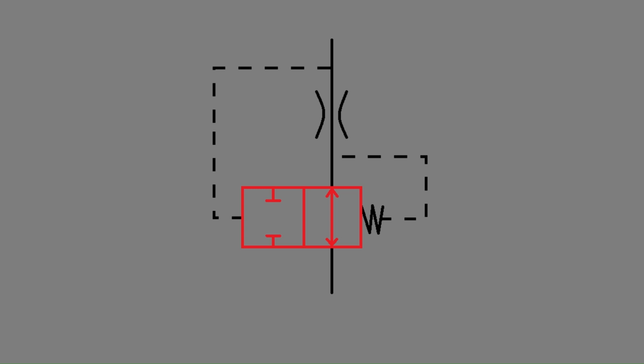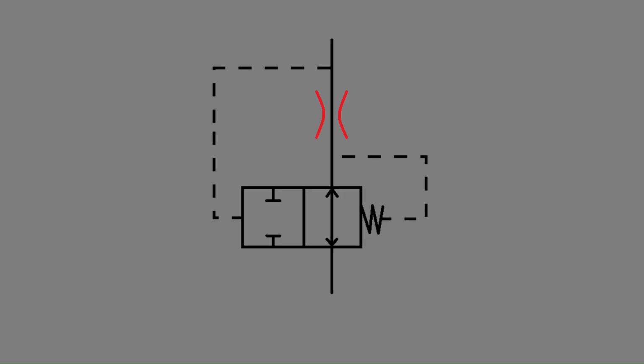At first glance, it may seem that the spring is setting the flow rate. A lot of other hydraulic devices behave the same way, where the spring is setting whatever we are controlling. However, the spring is setting the pressure drop, not the flow rate. It is the orifice that is determining what flow you will have at that pressure drop. So to change the flow rate, you would change the size of the orifice.